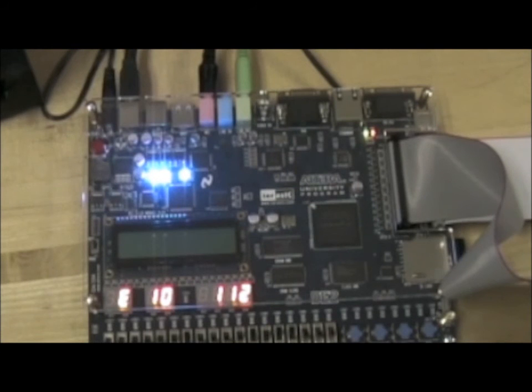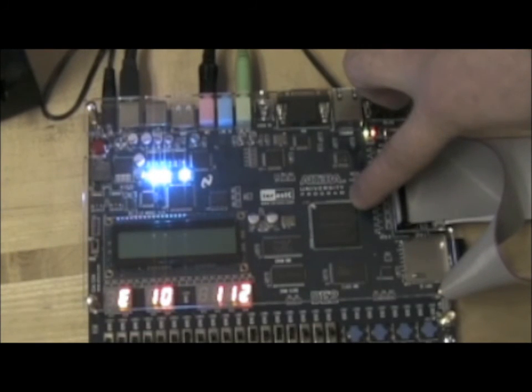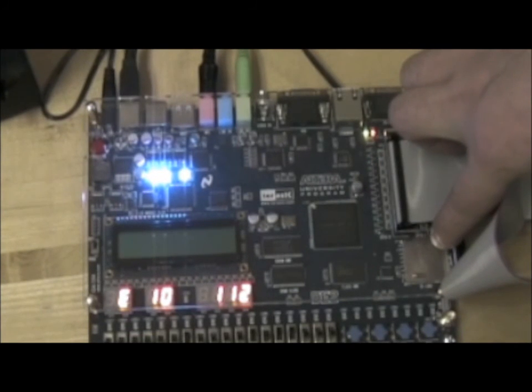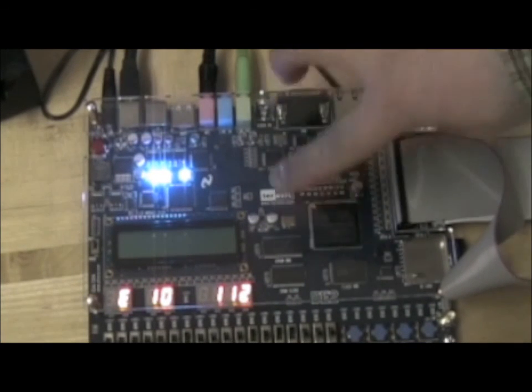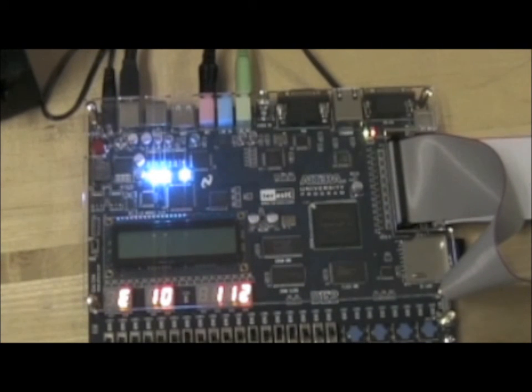The DE2 board has a lot of components on it. What we're actually using in this DE2 board is this, our Cyclone II FPGA, and the SD card where we're actually pulling the song files from, which can hold up to a gigabyte or so of data. We're using SDRAM here, the SDRAM component right here. That is our video processor's code. We're storing data on it, and we're using it to store program code as well.